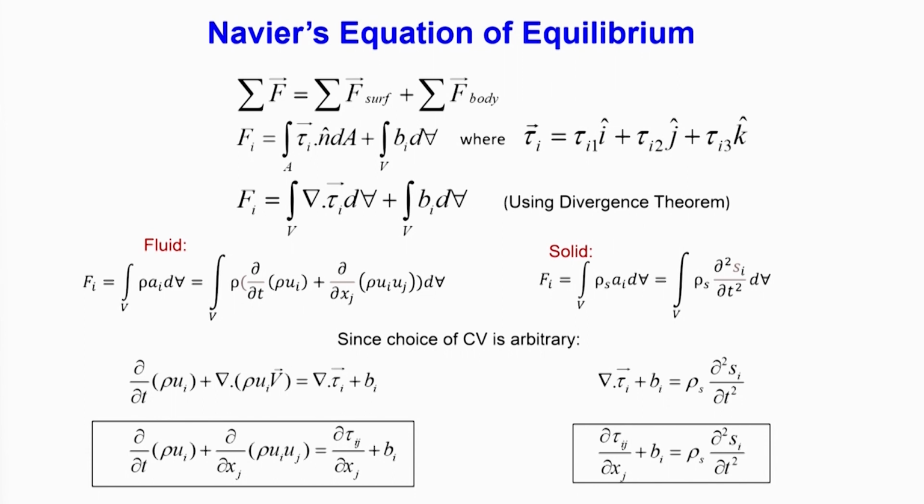fluid. Classical fluid will have viscous behavior and classical solid will have elastic behavior, and there are many materials, typically in physiology and bioengineering applications, which are partly viscous and partly elastic in behavior, that is called viscoelastic material. So when you have a viscoelastic material your stress is a function of both strain and rate of strain. Stress as a function of strain will be due to the elastic behavior and stress as a function of rate of strain is due to the viscous behavior.